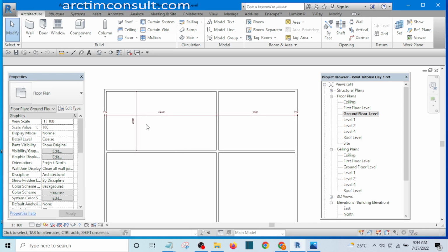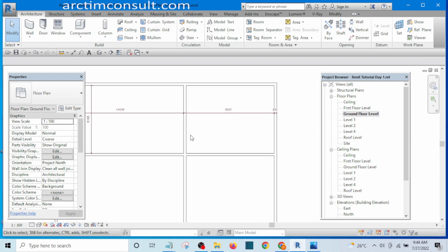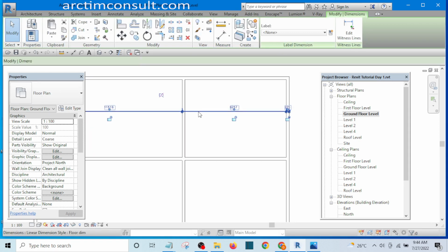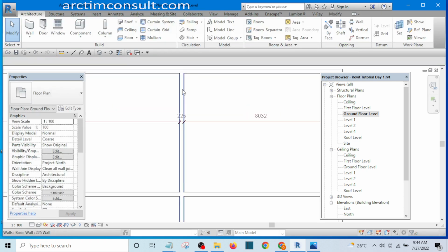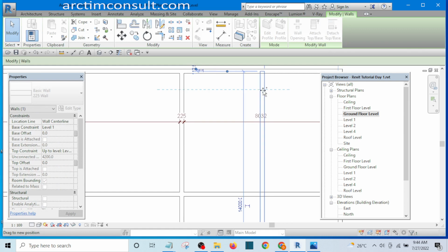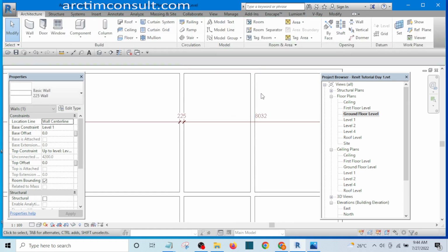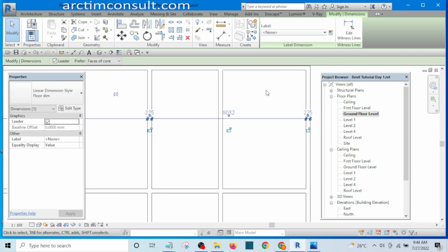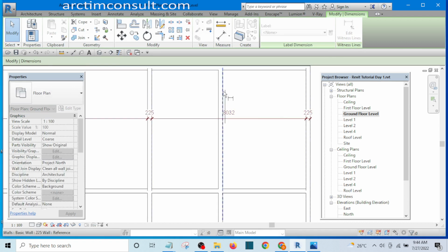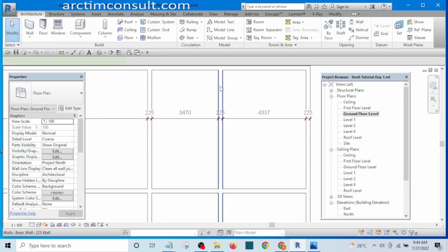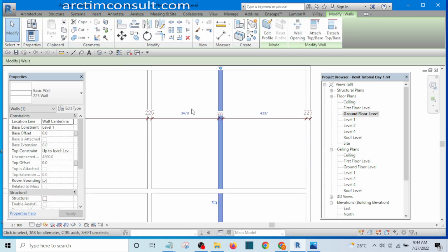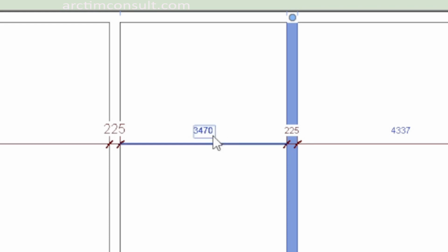That is the main lounge. Okay, then I will need to establish this toilet. There is a particular toilet that is here. I'm going to hold Control and copy this, then continue this dimension by clicking on Edit Witness Line, then select this particular wall and establish the width of the toilet.